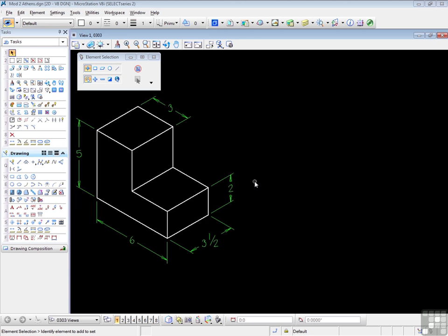reference line. To use existing views to draw other views requires that you are competent in the use of several AccuDraw shortcut techniques. Specifically, you should be able to use the O shortcut key to locate the compass at a tentative point, and use the Enter key as Smart Lock to lock lines to the compass axes, and Smart Lock again with a tentative point to constrain the length of a line, and Smart Lock again with the N key, which is the nearest snap, to constrain the placement of a line or the relocation of a tentative point. All these techniques were covered in the Level 1 videos.